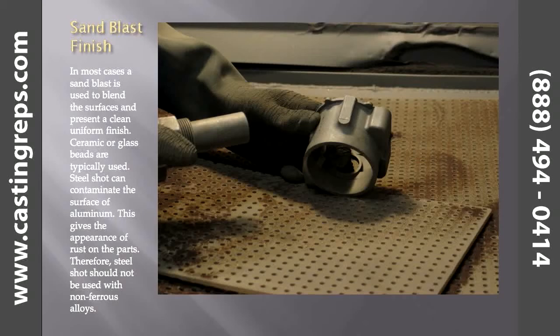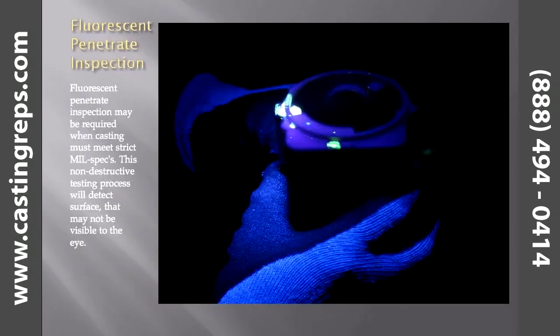Ceramic or glass beads are typically used. Steel shot can contaminate the surface of aluminum. This gives the appearance of rust on the parts. Therefore, steel shot should not be used with non-ferrous alloys.